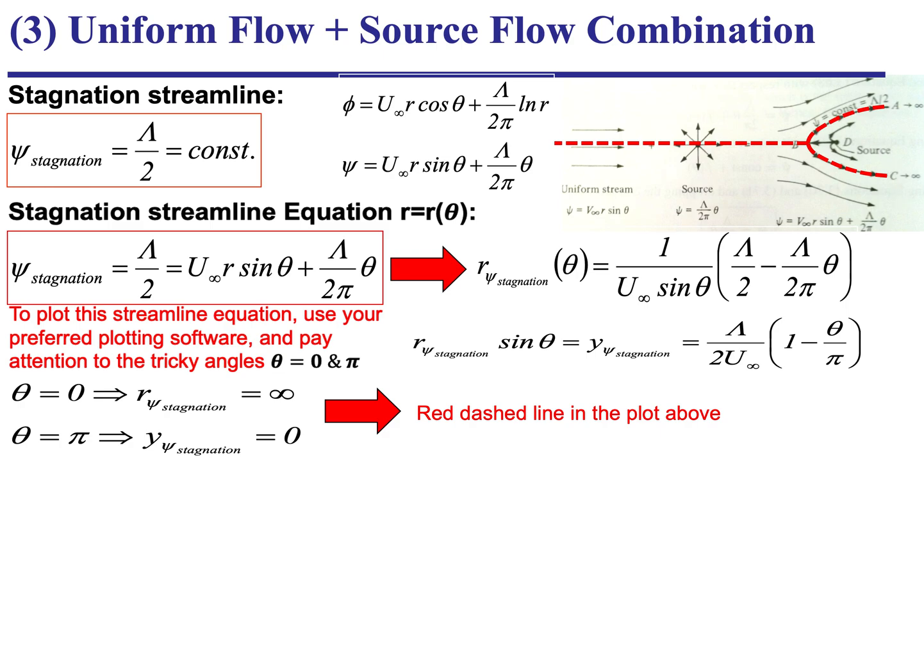Now, why are we doing this whole thing? What is the potential flow theory going to help us find? One, it's going to tell us what the flow pattern around the body is going to be. So it's going to give us streamlines, but also importantly, it's going to give us what the velocity on the body is. Remember, slip is allowed. And once we know the velocity on the body, we're going to be able to find the pressure over the surface of the body, which is a basic contributor to the aerodynamic force generation.